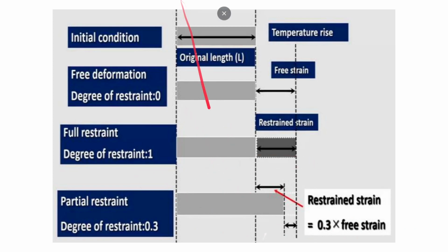These phenomena occur because the temperatures in the surface and the core are not equal, so the ability of deformation of the two areas will not be the same. Because it will not be the same, some kind of restraint develops, and if that restraint creates a tensile stress greater than the tensile strength of the concrete, then cracks will occur, which are called thermal cracks.